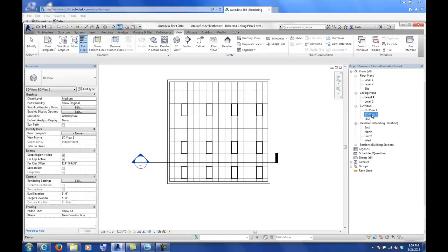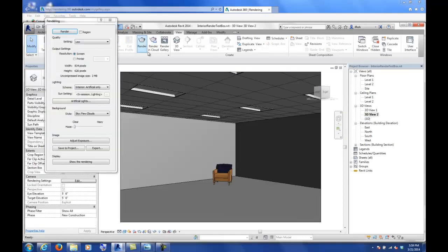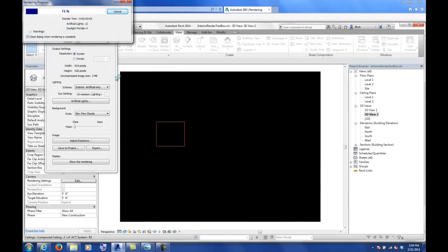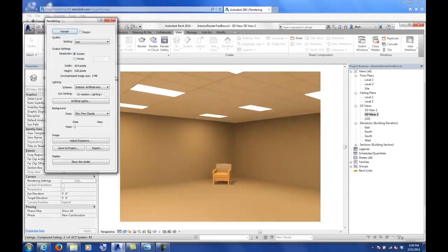Now in V-Ray, and I can go ahead and hit render here in this one. V-Ray and Rhino and 3D Studio Max, people always tell you about the 3-point lighting method. I don't know if anyone's still teaching that, but that's another theory for rendering, is that you do a big overall light somewhere, and of course in other programs the light doesn't necessarily render. So you do a big overall light, then you do like an accent light on something that you're trying to highlight, for instance like the chair, and then you would put another light somewhere where it's dim, and that's your 3-point lighting scheme, and that usually lights a room pretty well.